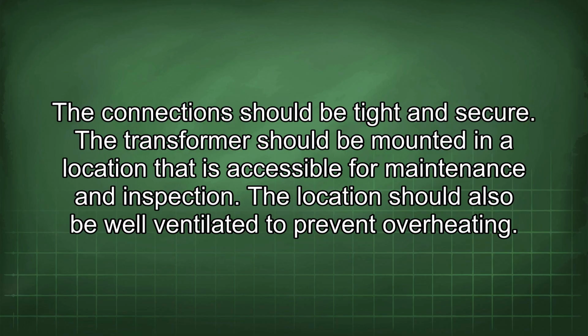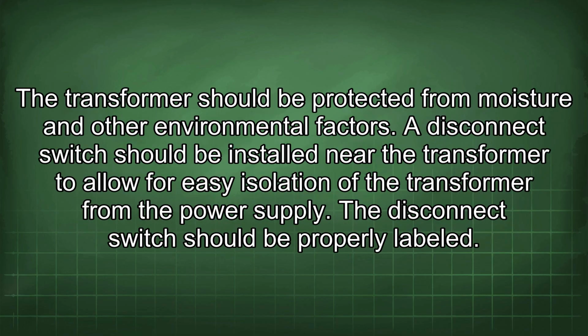The transformer should be mounted in a location that is accessible for maintenance and inspection. The location should also be well ventilated to prevent overheating. The transformer should be protected from moisture and other environmental factors.